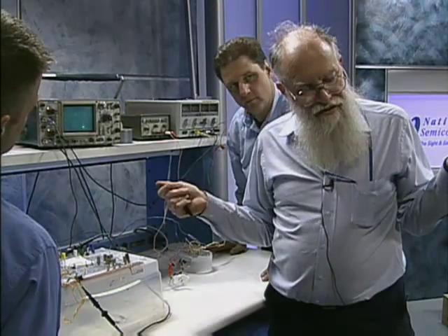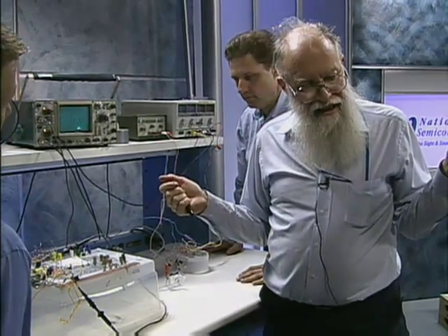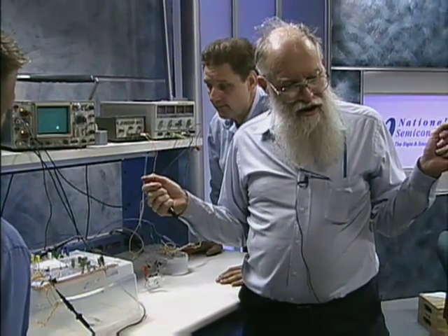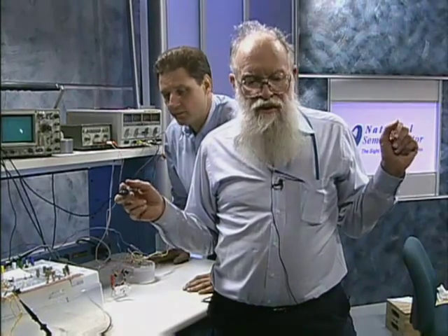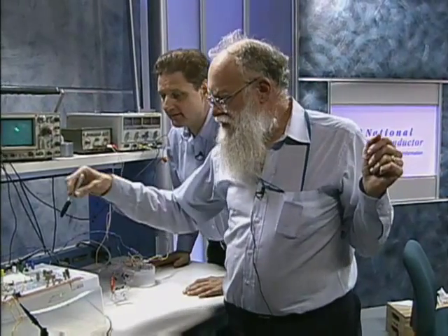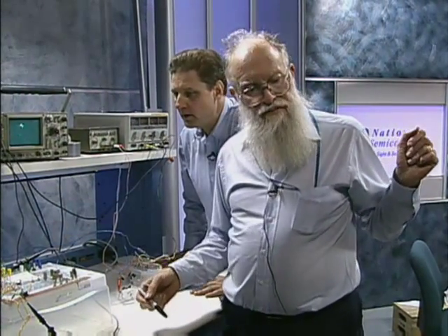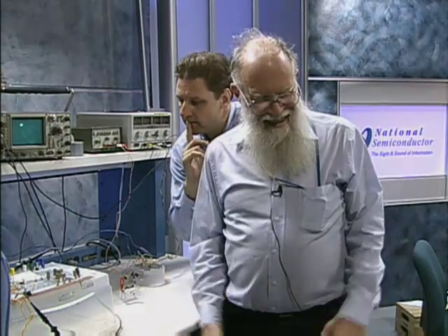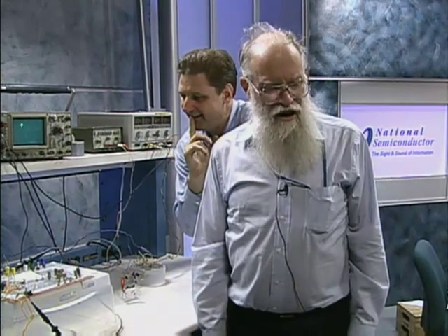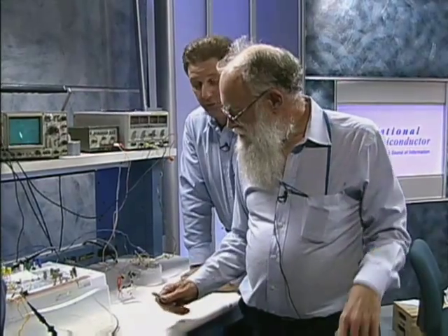The main point is, if you're trying to measure 80 amperes, 1 milliohm is lousy. Lots of watts. You need 0.1 milliohms to measure resistors. How do you measure a 0.1 milliohm resistor compared to this milliohm resistor? So we do milliohm and sub-milliohm resistor technology to help people measure 80 amperes. I don't approve of 80 amperes to run any circuit on, but if you have to, you can do that. I did an ECL test rack once, did 2,000 amperes.